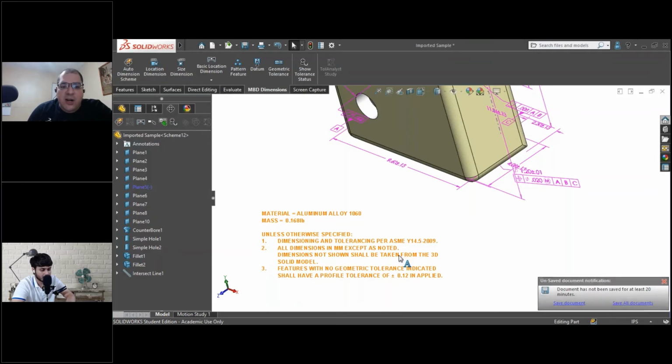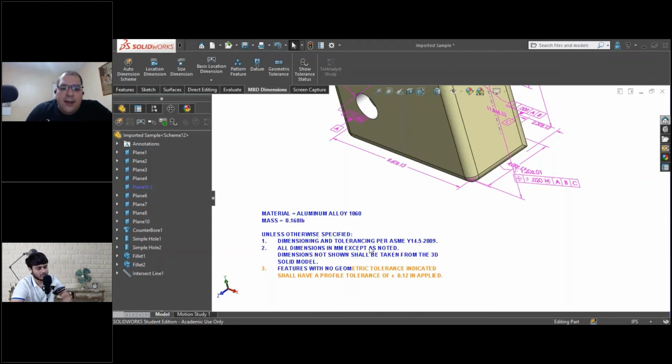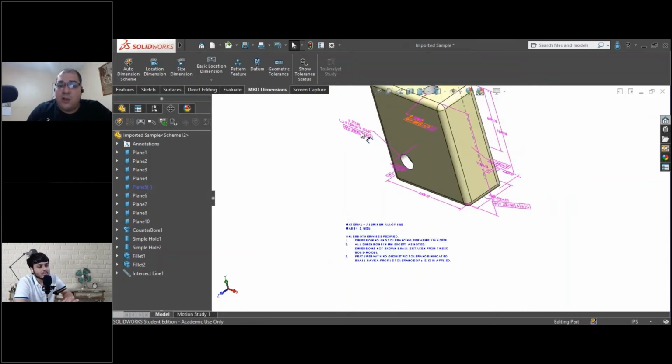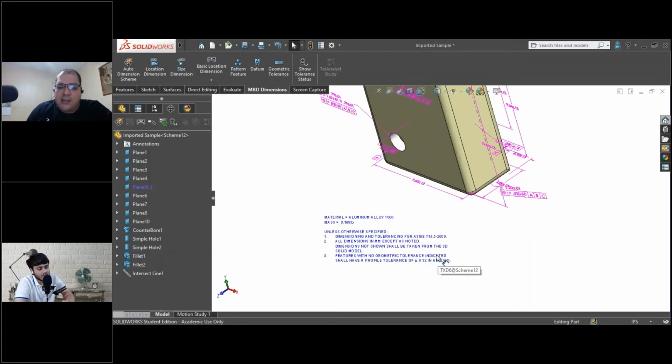We can bring those general notes to the 3D model directly, have them attached to the model and shown. So, for example, if some tolerance is not noted in the drawing, we can have the general tolerance attached, and we cover this part for the fabrication.